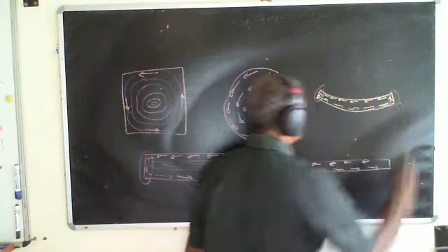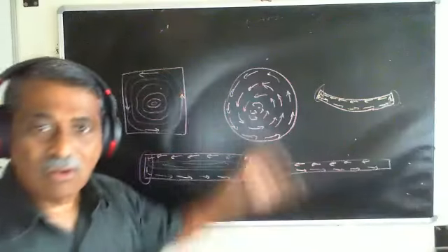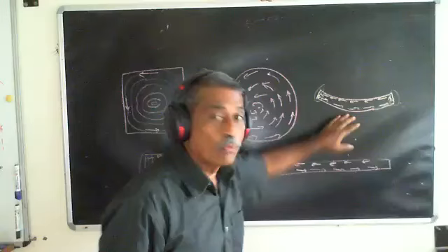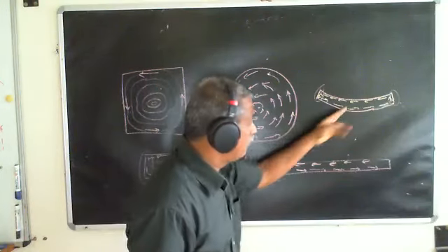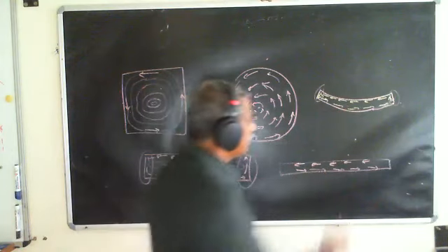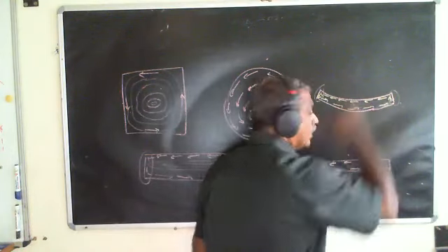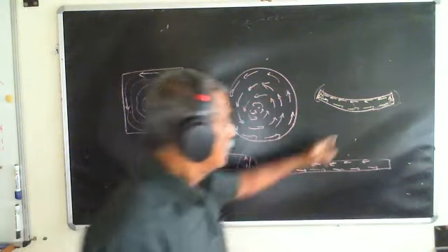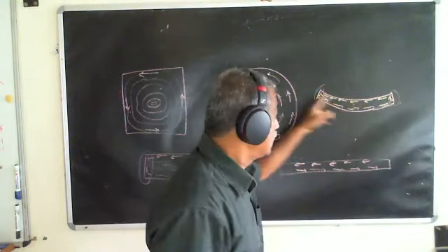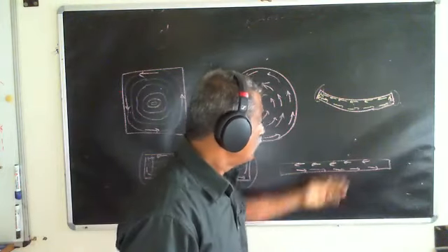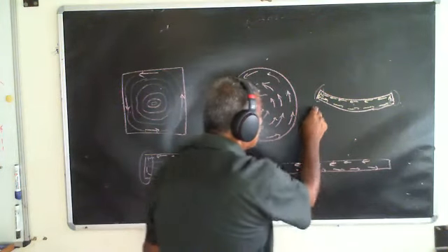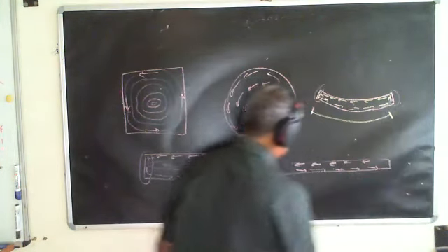It will have some very minuscule effect on the torque, but this is how the flow could be. Okay. Now, how is it different from here? Not much of a difference, because if I take the total torque by integrating these shear flows, I'll get something which will not be different from here as long as this length is the same as this length.